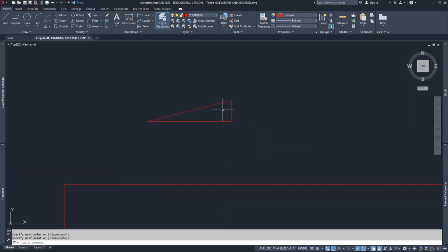If you'd like to change the slope, you can easily just grip this line, take it up, and let's say 1 inch. So now it's going to be a 4 in 12 slope, and I take this angled line and connect it. So maybe that's better. You pick whatever you'd like. But now that I have the angle, I can delete these 2 lines right here, and then I can take this line and move it. So M, enter, select the line, enter, from this endpoint over to that endpoint.